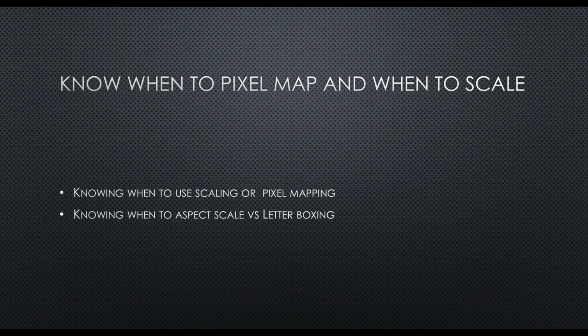Knowing when to use aspect scale versus letterboxing, and when to use free scaling. In my opinion, free scale should almost never be used. However, it's there, and on almost all the NovaStar VX6S, VX4S, Nova Pro Ultra HD, and all those other processors with the scaler built into it, you have a function called auto scale.